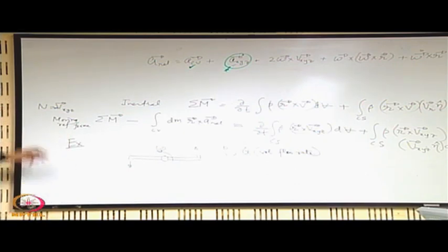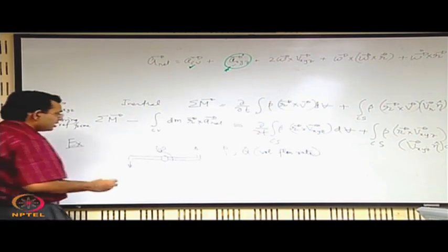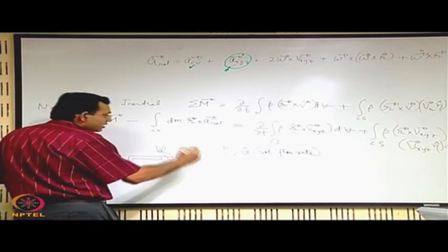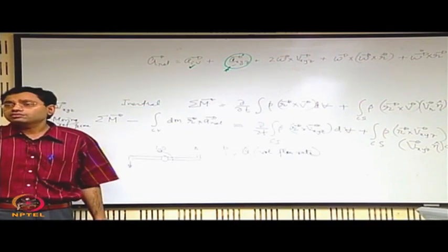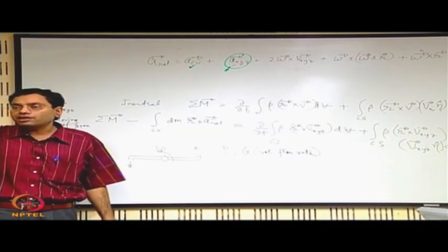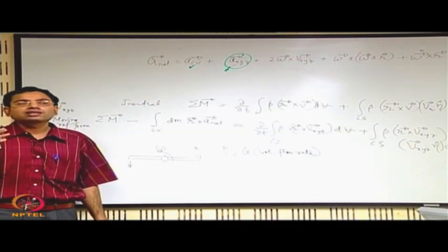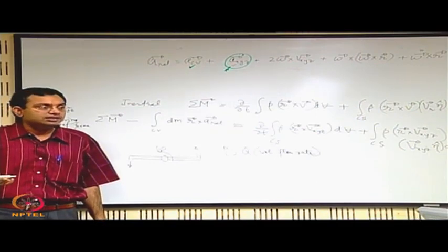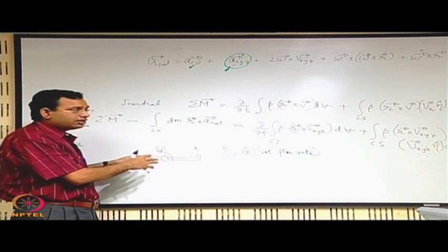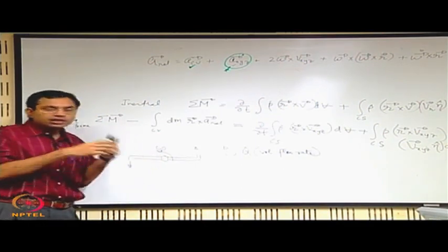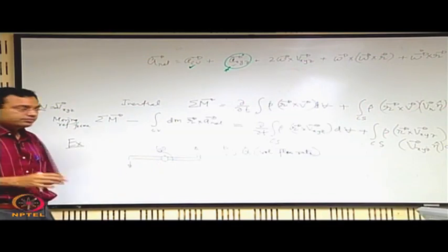We start with the moving reference frame, that is, as if we attach the reference frame with the sprinkler arm, which is rotating with some angular velocity which is a function of time, and therefore it is subjected also to some angular acceleration, but it is not translating. So, now we have a control volume which is a rotating control volume, but not a translating one.